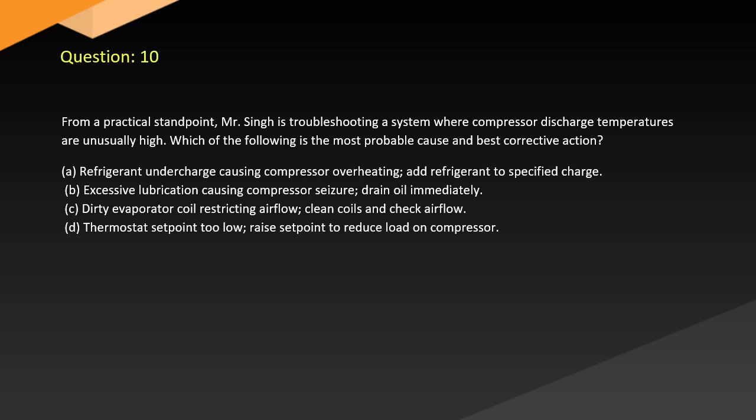A. Refrigerant undercharge causing compressor overheating. Add refrigerant to specified charge. B. Excessive lubrication causing compressor seizure. Drain oil immediately. C. Dirty evaporator coil restricting airflow. Clean coils and check airflow. D. Thermostat set point too low. Raise set point to reduce load on compressor.